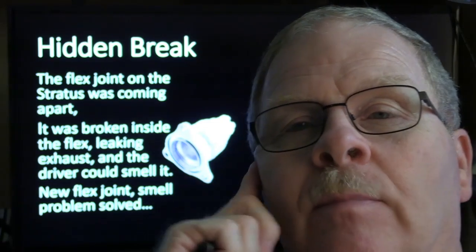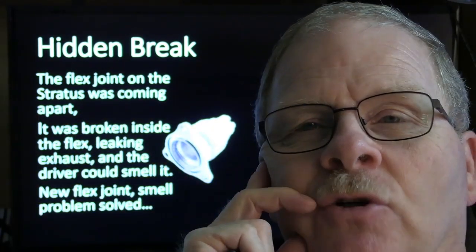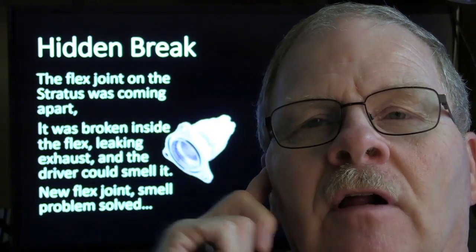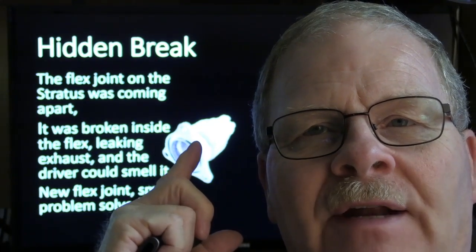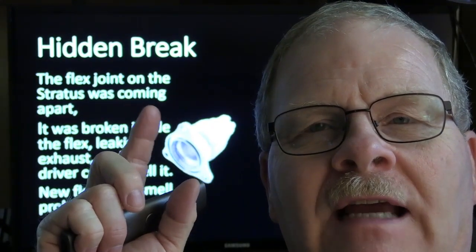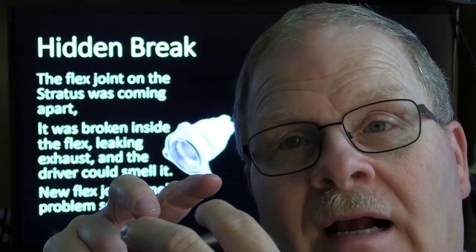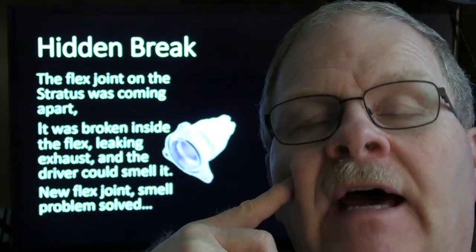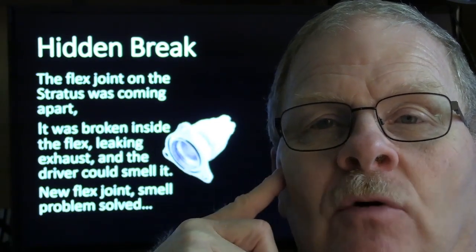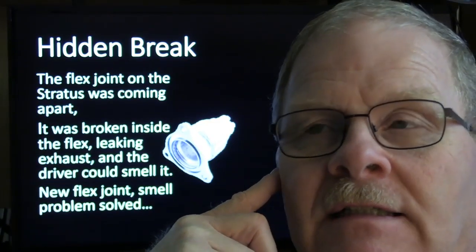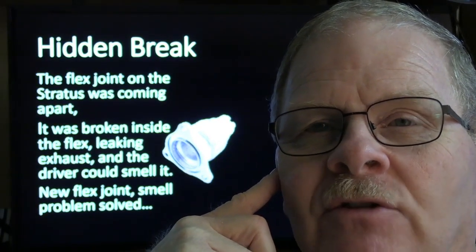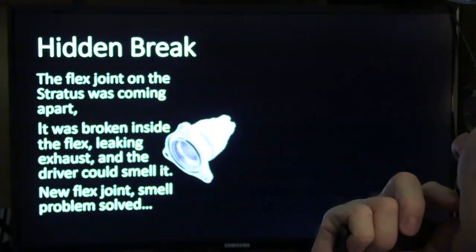And so in that particular case, you got a couple of choices. It's part of the catalytic converter, but you can buy just that joint nowadays, and you can whack off the front of the catalytic converter and weld that back on there. You got to make sure it's indexed right and all that. And you can just replace the flex joint if there's nothing wrong with the catalyst. It's a lot cheaper to replace the flex joint than it is to put a new catalyst on it.